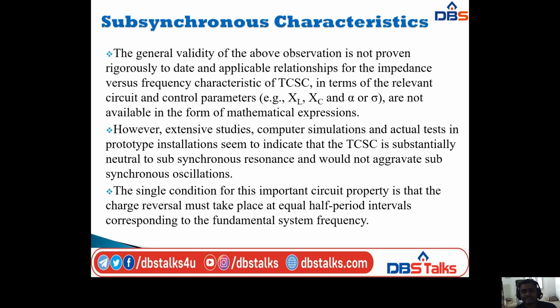However, extensive studies, computer simulations, and the actual tests in prototype installations seem to indicate that the TCSC is substantially neutral to subsynchronous resonance and would not aggravate the subsynchronous oscillations.